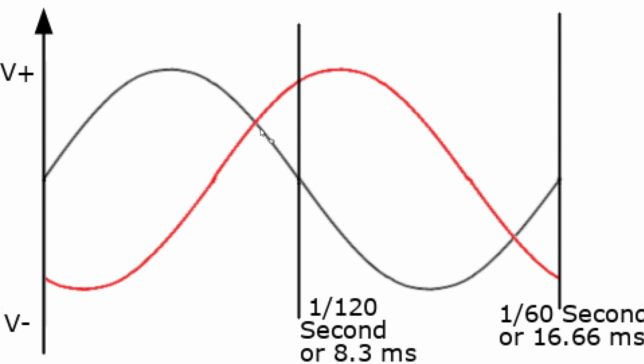And then again, they start going further and further apart. This time it's a positive voltage because the red wire is above the black wire. We're measuring from the black wire. And it's getting further and further apart until this one starts to approach its hump and the red wire is starting to leave its hump. And so on, getting closer and closer together till again we reach zero and they start going further apart again.